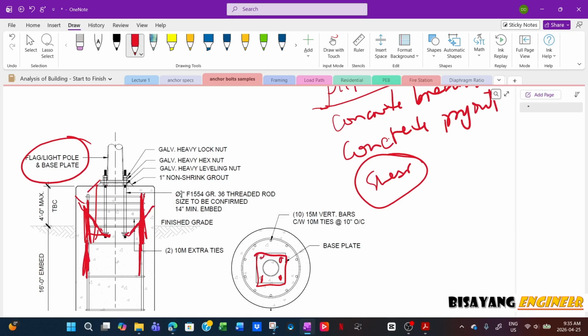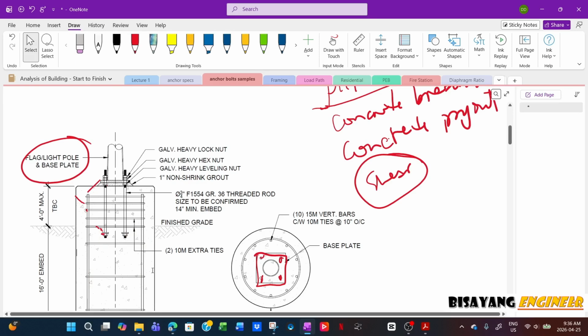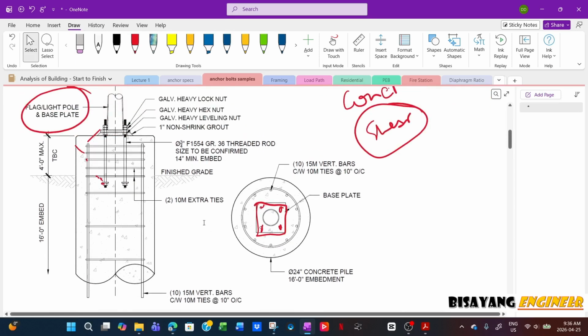Before, I already did a minimum embedment based on actual force, but most of the time what governs is making sure that the shear plane will cross over into the reinforcing bars, and that would grab the rebars, and they transfer that to the foundation. If this is a pile, then the pile can handle that load.